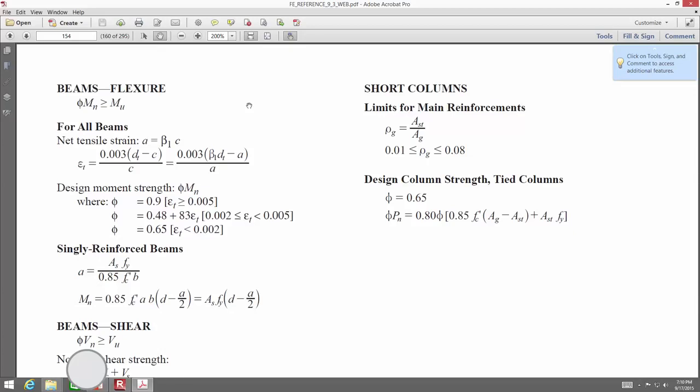One other piece of advice that I would give you is that when it comes to beams, it's probably unlikely that you're going to be doing heavy design. If you remember from concrete design, if you're designing a beam, it's a highly iterative process. I mean, you're making guesses at the beginning, like, oh, the beam's about this deep and about this wide, and then from there you have a weight that gives you a dead load and you go from there. It's very open-ended.